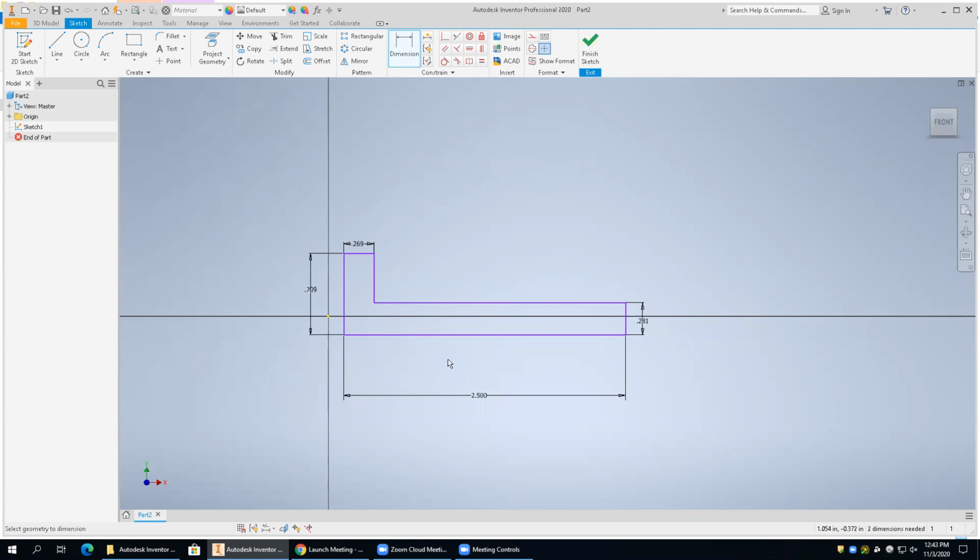Just click on the dimension, open up that box, change the value that's in there, and hit the green check. Okay. Anybody not finding that to work? You're not finding it to work. All right. You have dimensions on there. Hit the escape key. Click on the box. Just click it. You have to double click for some reason, but you shouldn't have to. I usually just click it.